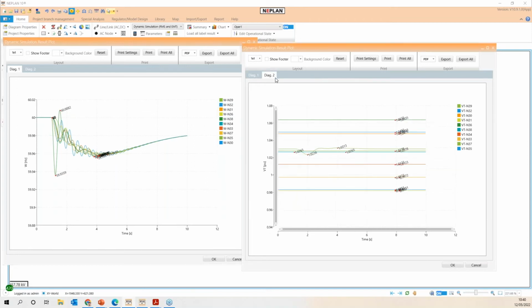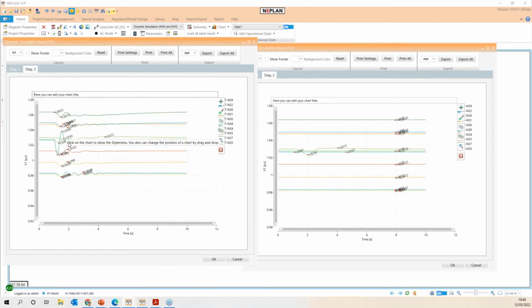and if I show here the voltage response, we can see how the performance using this kind of models that use power electronics can support faster implementations, but it will depend on the model. In this case, we have the comparison between the generation with synchronous generators and the generation with inverters using a grid forming model.